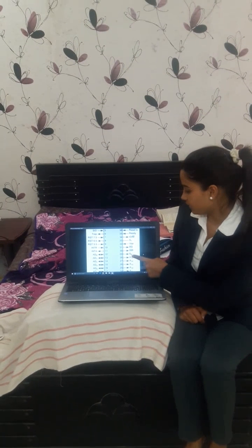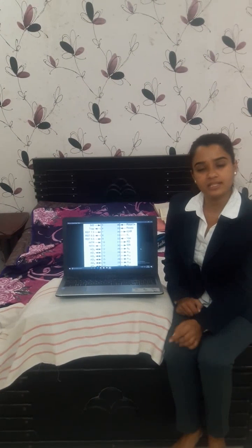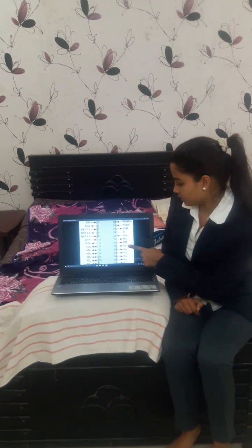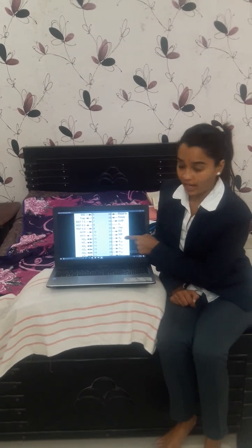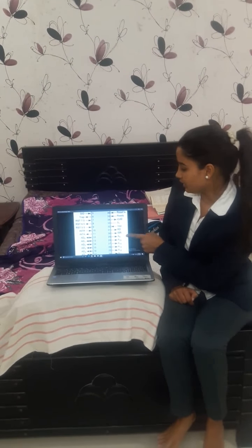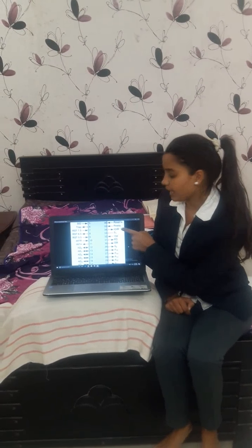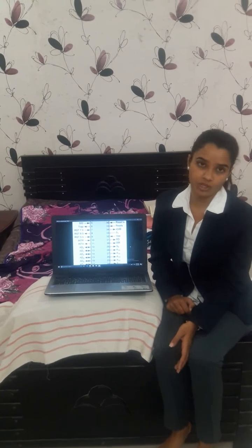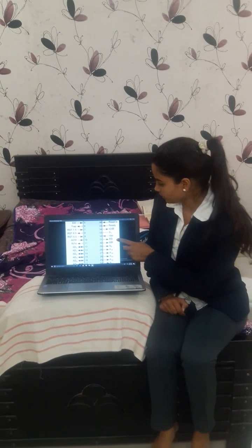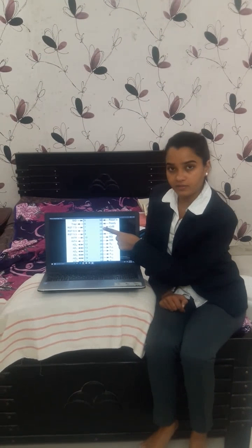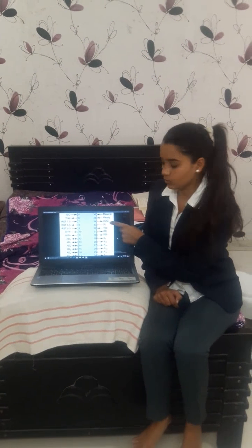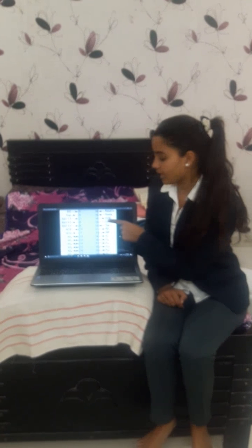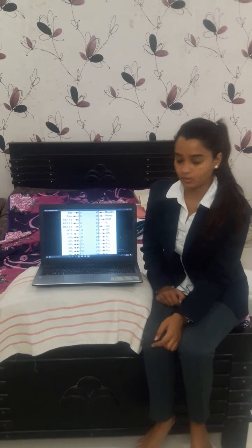Next are pins 29 to 34. These are called the status and control pins, namely S0, S1, read, write, and IO/M. The S0, S1 and IO/M function together. They are related to input output and memory. When pin 34, that is IO/M, goes low, it means a memory operation is going on. When it goes high, that means an input output operation is going on.